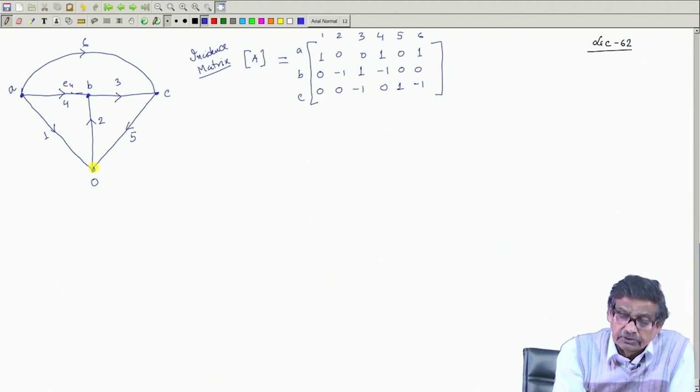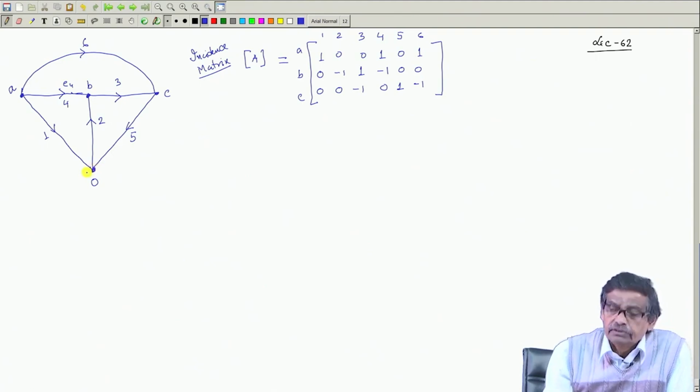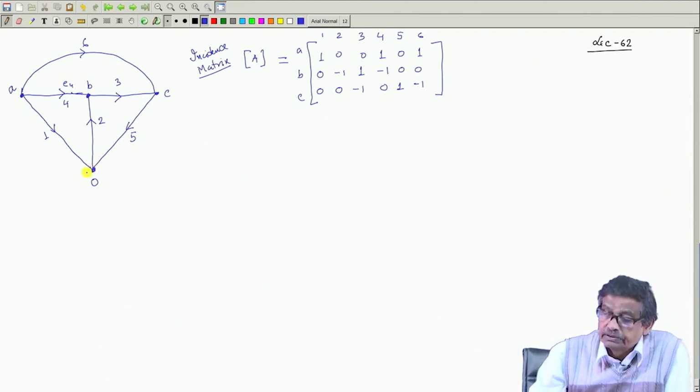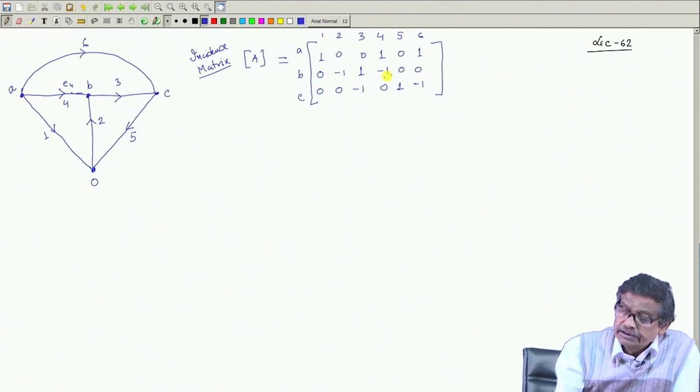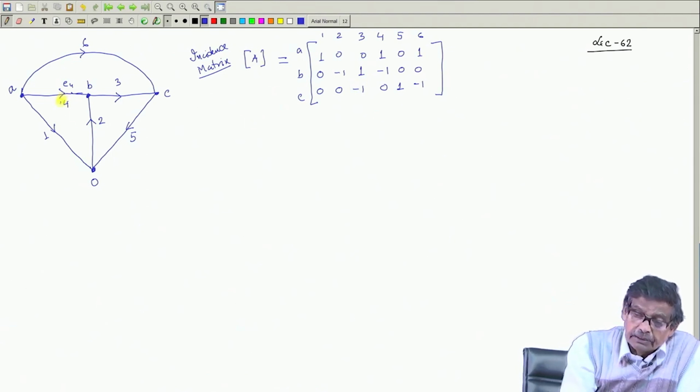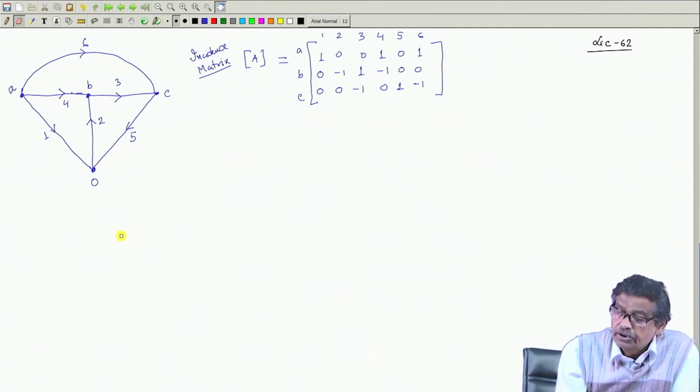We are not writing down KCL at O, because that is not going to give you any new equation. And we also discussed the size of the matrix. But what was the implication? The arrows mean the branch currents in this direction, and the voltage of this branch is VE4 with this side plus, this side minus, consistent with the direction of the current assumed.